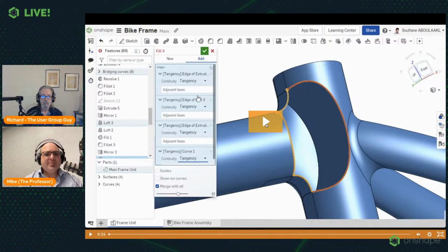So here's a quick example of where this new function can come in handy. Or I shouldn't say function, because it was an addition to multiple features: this particular item in the fill command and then the loft command, because you can use fill and loft almost interchangeably to a certain degree. You could literally create this filled in shape with a loft if you wanted to, or with a fill.